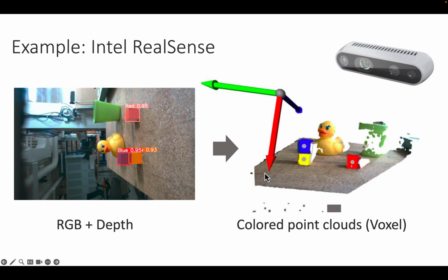And you can now draw this scenario here using these voxels, and you see only the front-facing parts of the elements here. And this sensor in this case doesn't range very far, so it has a hard time seeing this cup which is in the background. What you also see here is the coordinate system of where the camera is actually mounted. So the x-axis is facing down and the depth is usually in the z dimension. So you see this very nicely here because you are already used to the z axis always being blue.